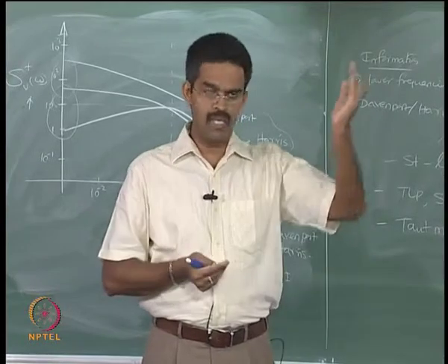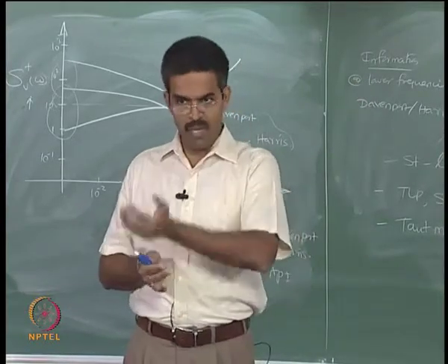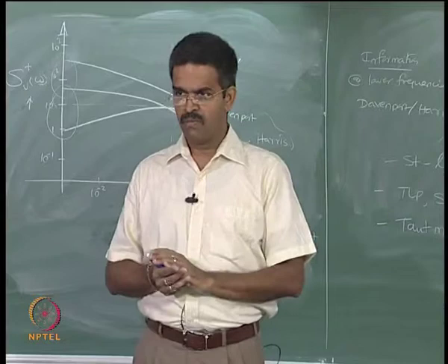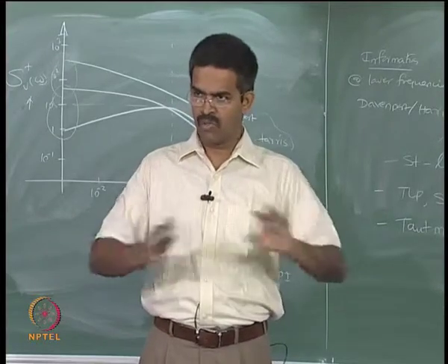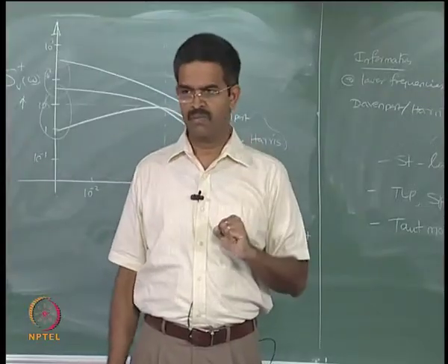We started with Airy's theory, and we understood there are higher order theories available like Stokes fifth order. They are available in the literature, and this course will not cover those aspects in detail. We also discussed how to handle the nonlinear drag part. We have also discussed how to handle the damping part and what approximate value is suggested by the literature for flexible or bottom supported cylindrical structures, or structures having cylindrical members.